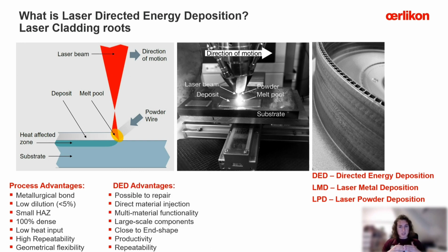If we talk specifically about DED advantages, in my opinion, we should focus on three of them. The first is that it is possible to repair your components. That means if you make a mistake during the process, you can always machine a certain area away and start continuous rebuilding of it. Secondly, we talk about high material efficiency.